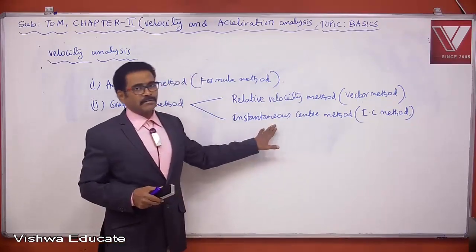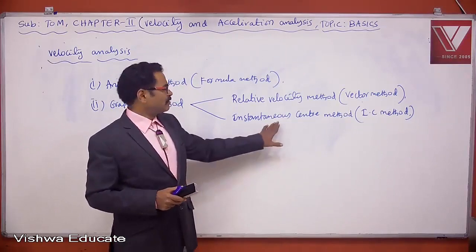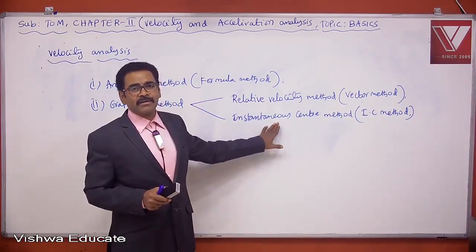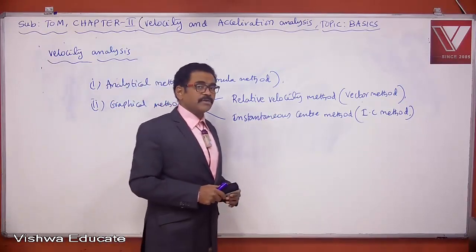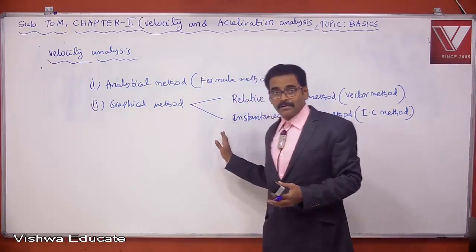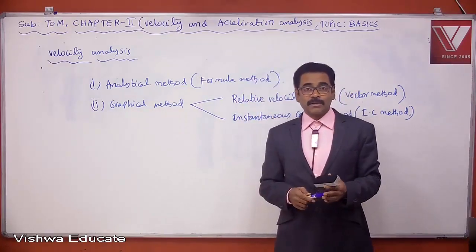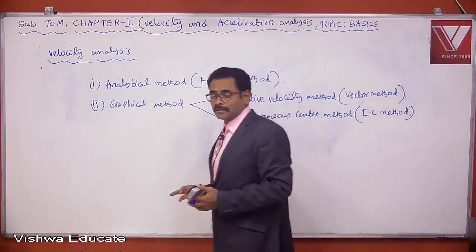But instantaneous center method, right? If you want to perform acceleration analysis also, this method may not be suitable, because by using instantaneous center method, you cannot find various accelerations of the mechanism. That is the drawback of instantaneous center method.